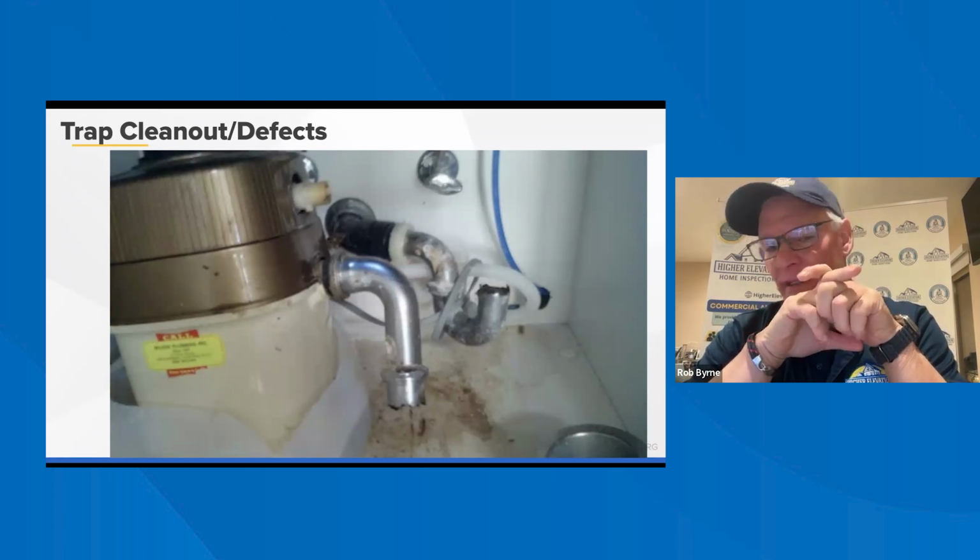Pipes located less than 1.5 inches from the edge of the studs, joists, or rafters must be shielded from damage caused by nails, screws, or fasteners. So that's something where, if the drain or a pipe is going through and it's too close to the stud, then on the outside they'll put those pieces on. I think we might have some pictures of that in the next one. Use of shields, steel shields at least 1/16 of an inch thick, must be installed to cover and protect pipes where holes or notches occur in framing, which you see on that picture here.